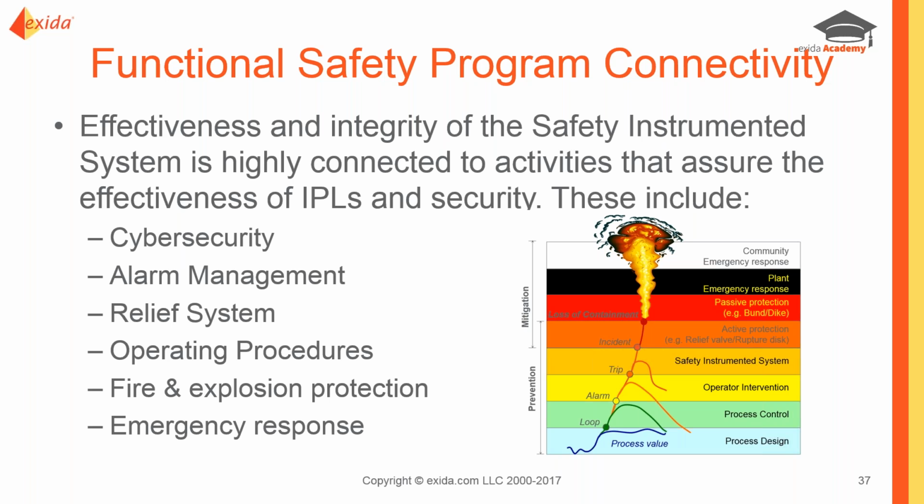Cybersecurity, we're interested in that because we want to make sure that the safety instrumented system is secure and that it can't be compromised from outside. Items such as independent protection layers, we may need to harmonize those with our risk management or SIL determination process. What we credit for, say, operator response to an alarm may be different where we have a